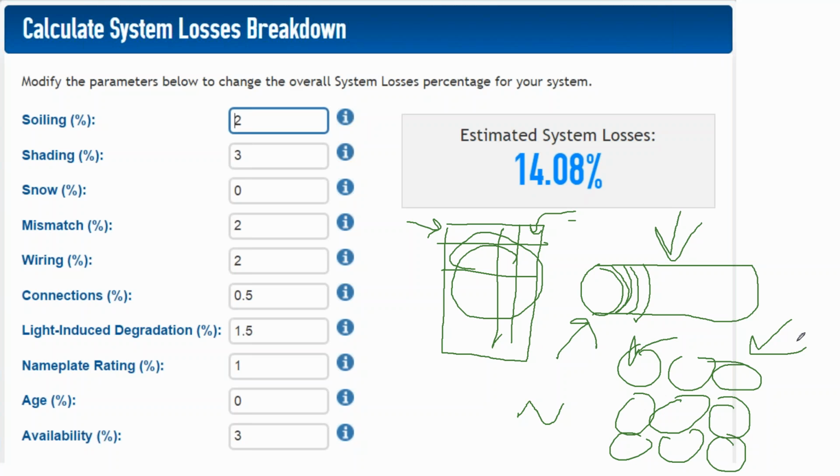Even within that, the tier goes from 290 watts up to 300 watts, and then it's labeled as a 300 watt panel. So I open up a pallet of 290 watt panels. Some of them will produce 290 watts. Generally, the tolerances today are -0 to +5.